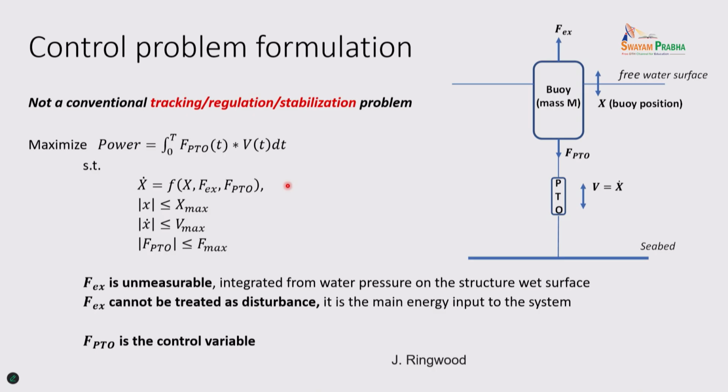No. If you look into linear quadratic control, people care about the x square and u square. This is the RQ term, and they normally don't care about the cross diagonal term. Here, in wave energy control, the cross diagonal term is more important.